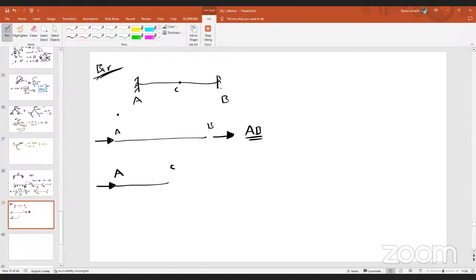So even if you cut at any point, you can see only the axial internal force. So even at point C, you can only see 1 reaction. Why? Because as it is a bar problem, they will resist only the axial forces. Similarly, you can look at CB. We already know at C 1 reaction will exist and at B 1 reaction will exist.